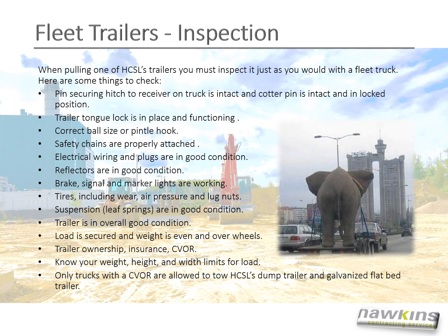When pulling one of Hawkins' trailers, you must inspect it just as you would a fleet truck. Here are some things to check. The pin securing the hitch to the receiver on the truck, make sure it is intact and the cotter pin is intact and in locked position. Check the trailer tongue lock, make sure it is in place and functioning. Make sure you're using the right ball size or pintle hook. Check the safety chains. Check the electrical wiring and plugs.